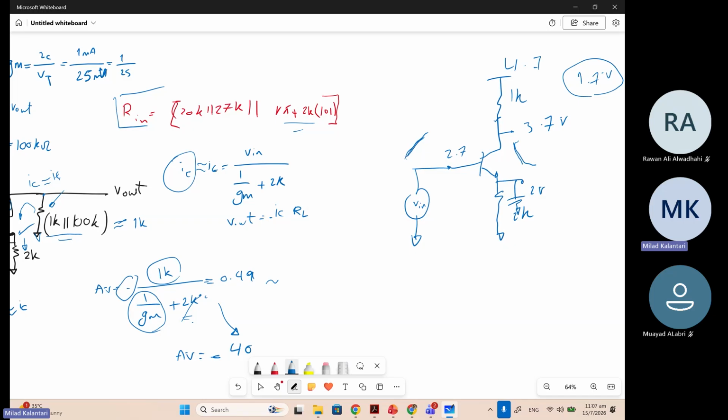And when you are applying some AC on top of this, then this voltage starts going down, right? Until this voltage reaches what? I mean, the VC is becoming lower and lower, right? Until it reaches the VCE sat. VCE sat, right? The saturation, which is normally like 0.22 volt. Do you remember? So it means that this voltage from the DC can go down to like, okay, another thing.